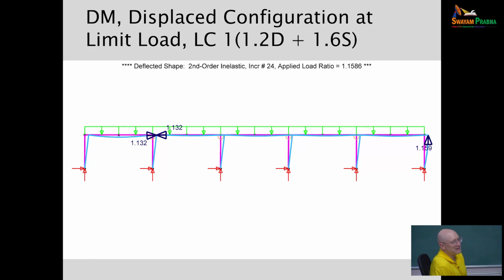I was asking, is the effective length method typically conservative because of the underestimation? So the question is whether effective length is typically conservative because of the underestimation. It can work either way, and we're going to see that the results for this frame end up being conservative. But we could create other problems where it goes the other way.